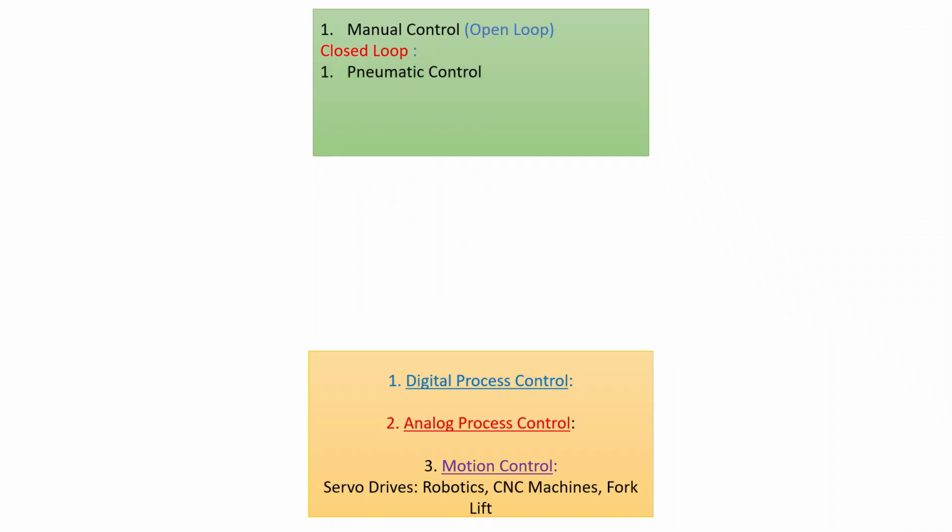First, pneumatic control, in which logics are operated by air pressure, which is then given to the pneumatic cylinders to make or break the electrical circuit. Second, relay ladder logic, in which electrically operated relays are used to make or break the circuits, and the ladder name indicates that the logic will take the form of ladder-like steps. It is designed as per electrical IEC standard.